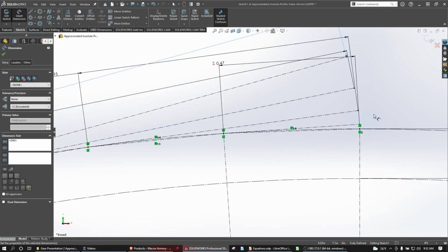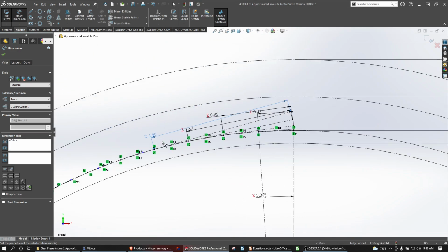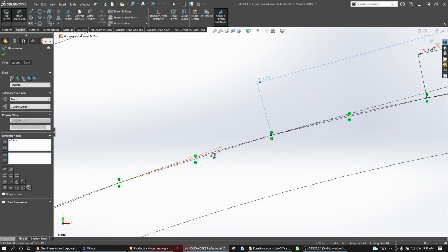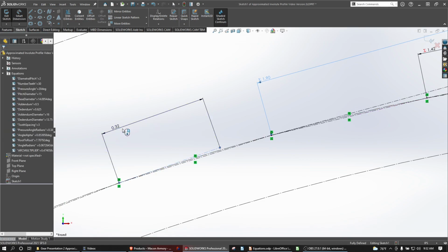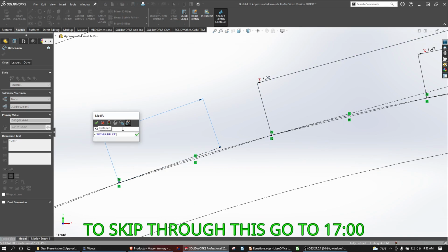As you can see, these points start carving out a little involute profile. They fall where the involute profile falls, and we're basically using these line lengths to act almost like a string that will be at the correct length as it unwinds around the base circle. Arc multiplier times 5.